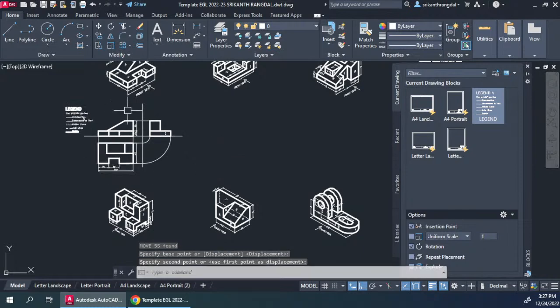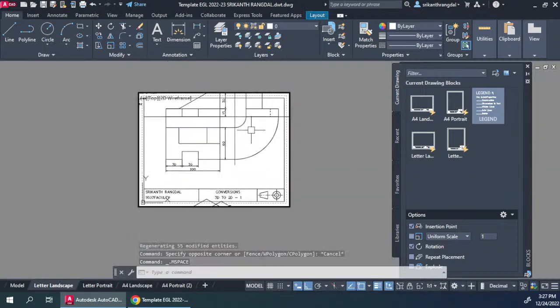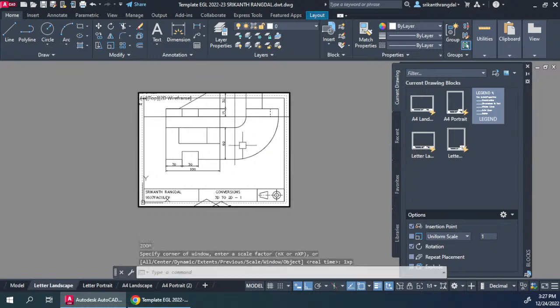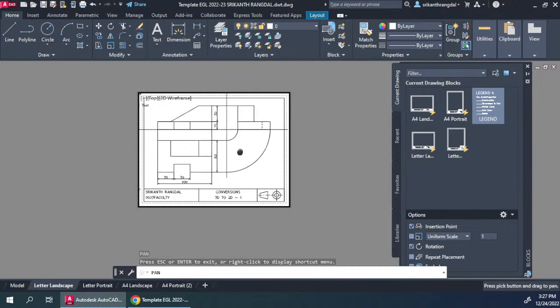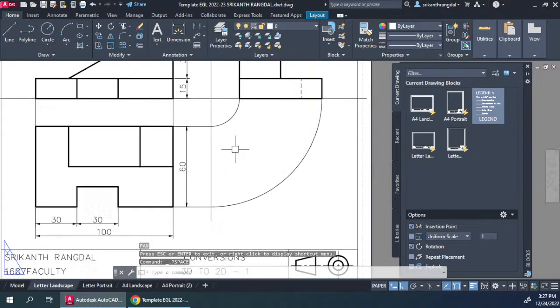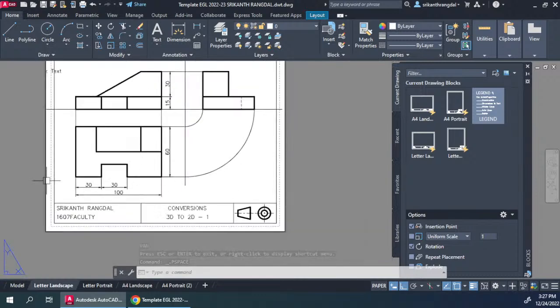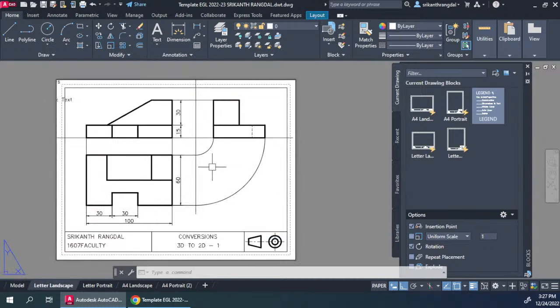We have to place it such that there is sufficient distance from the other diagrams over here. And now when we try to fix it, again Z enter, 1xp enter, and then P enter. I can adjust it, double click outside. Now you can see that the diagram is placed correctly and it is set to 1:1 ratio. And now when the print is taken, it will come out perfectly without any problem.